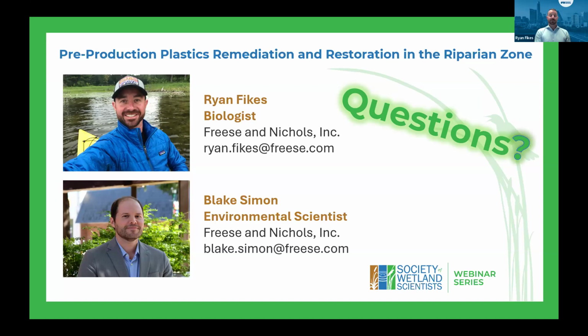Both the upland and aquatic portions are removed all at the same time. Before any backfill is done, we skim all the surface waters and do a cleanup using industrial vacuums along the shoreline itself. And that's when both parties come back in, both our client and the plaintiff, walk those sections, and visually see that everything is free of plastics before we can backfill and cap those areas. So it's through mainly those simple BMPs and segmenting it into bite-sized pieces.